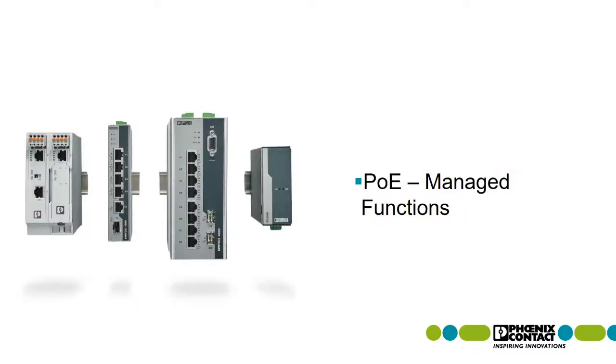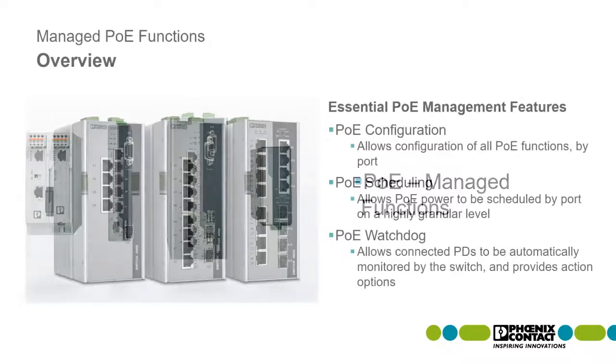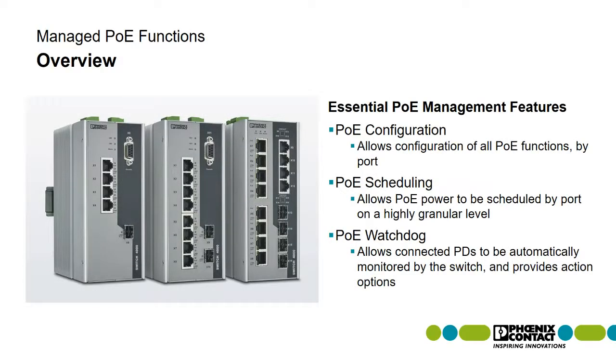So now turning to the managed functions that we wanted to discuss. Taking an overview look at it, these are what separate an unmanaged PoE switch from a managed PoE switch when it comes to the Power over Ethernet portion. You've got PoE configuration, and this allows a breakdown by port configuration of all your PoE functions. PoE scheduling, that allows the PoE power to be scheduled by port on a very granular level.